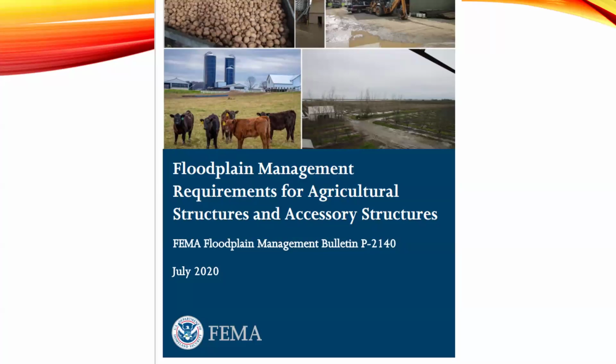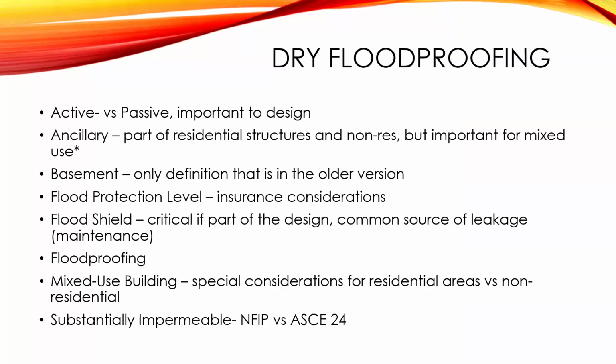The type of structures that would pose a danger to the health and safety and welfare of the public. Again, repetitive loss situations. And there's more model language for ordinance amendments because FEMA highly recommends that you adopt that language into your ordinance if you're going to allow for that wet floodproofing and those types of variances.